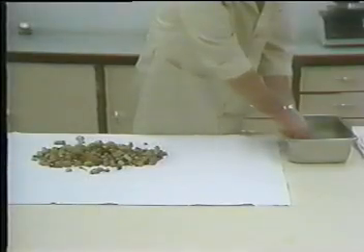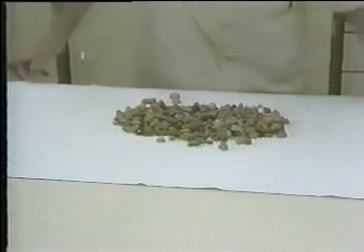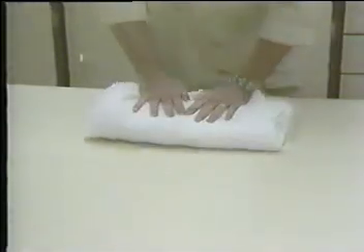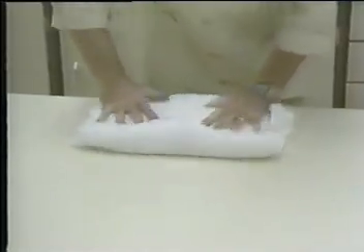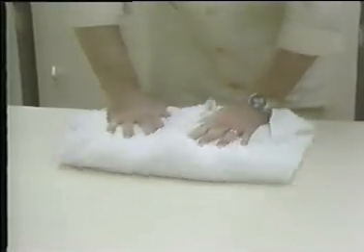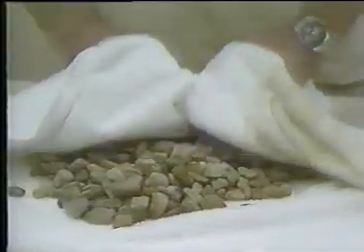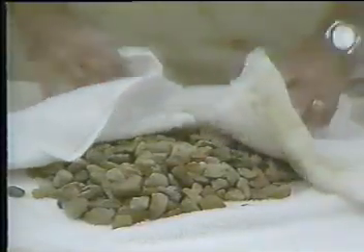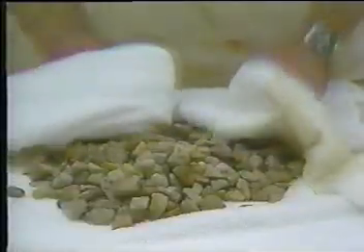After the 24-hour soaking period, remove the test sample from the water and place it on a large absorbent cloth. Dry the surface of the aggregate by rolling it in the cloth until all visible water is removed. Fans or blowers may be used to assist drying. Wipe large particles individually to make sure all surface moisture has been removed. Complete the surface drying before the water has a chance to evaporate from the aggregate pores.